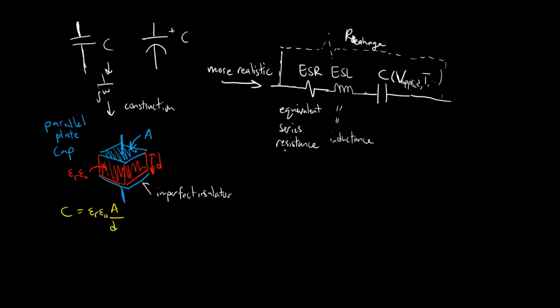Cool. So of these things, then there's a lot of variables. It all varies depending on construction, all these different values, right? ESR, ESL, C, whatever. The most important aspects, we might say, or the non-ideal aspects that we're going to talk about anyways, well, one is the loss associated with ESR. And the second that's kind of interesting and important that I want to talk about is the self-resonant frequency.